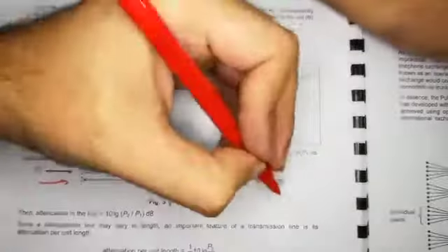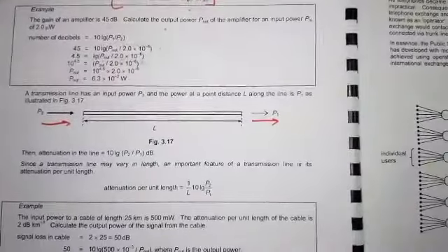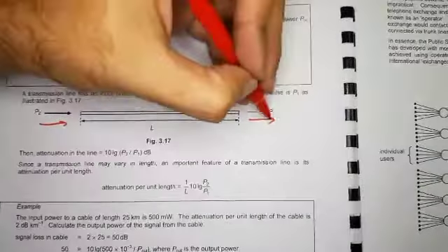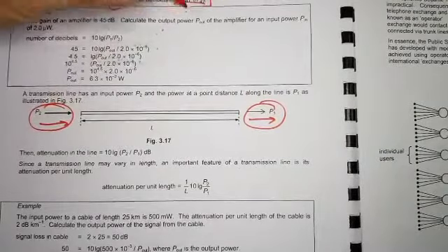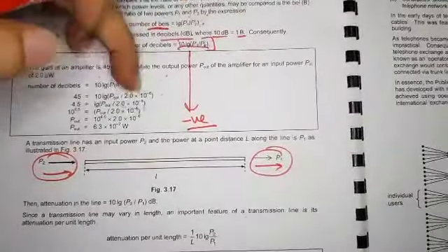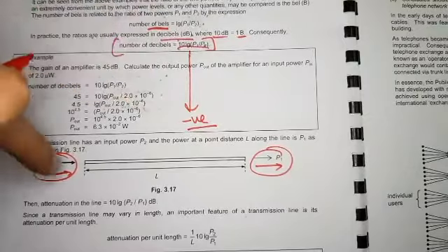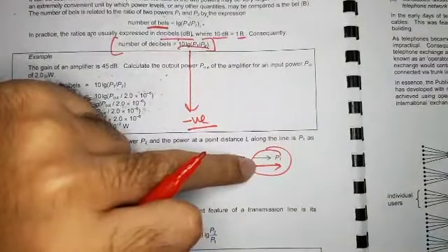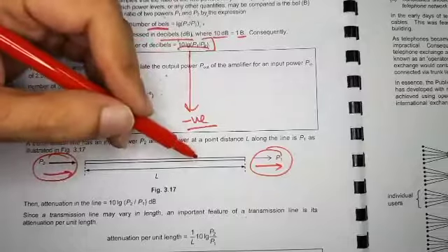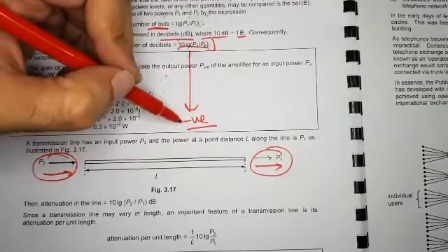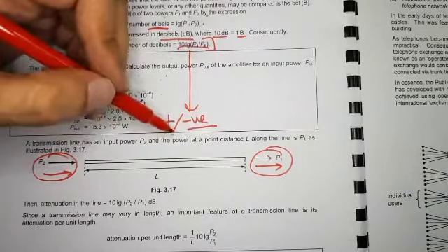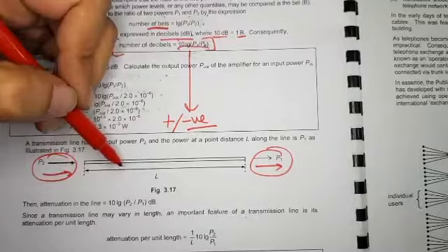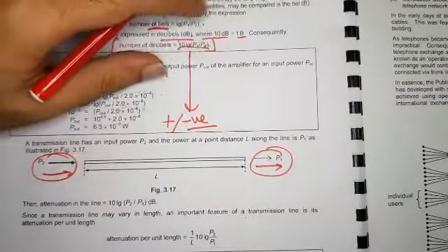An important thing you need to remember is to use a little bit of common sense when you use these answers or questions. For example, P1 will have a much smaller value than P2 does. So if you put this into this equation, it's going to give you a negative value. If it gives you a negative value, that basically means the signal is being attenuated. If you mistakenly put P1 on top and P2 on the bottom as a denominator, it's still attenuation. That doesn't change the truth, but the value will no longer be negative. It's going to become positive. If it becomes positive, you need to understand that it's positive because the value which is going in is higher. The cable is still attenuating. It's still losing energy.